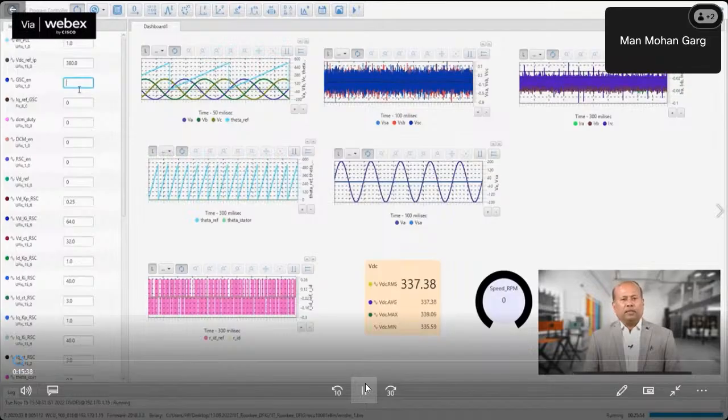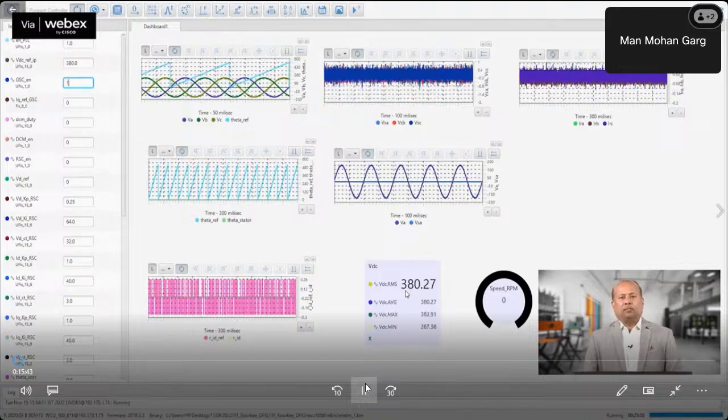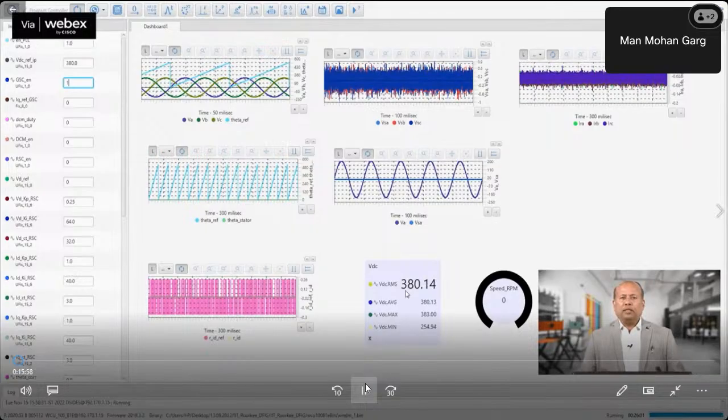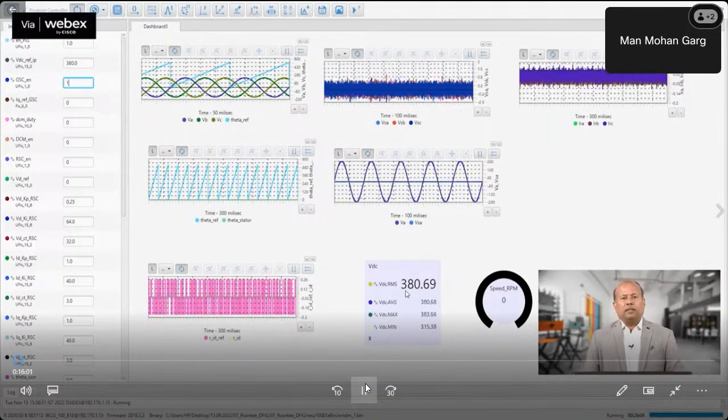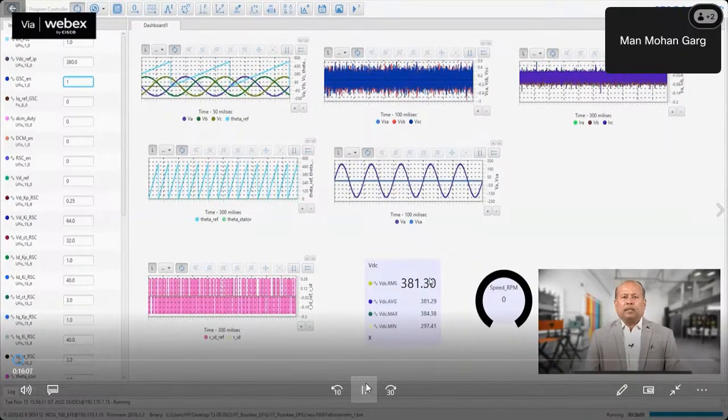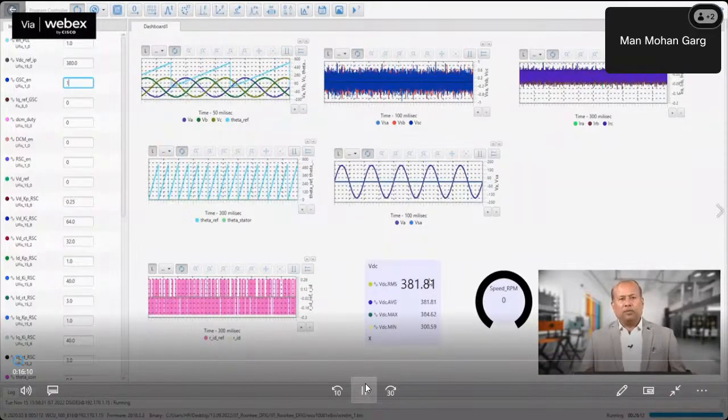Once the DC link is charged, we enable the GSC control to maintain the desired DC link voltage, which is set to say 30 volt greater than DC link voltage, that is close to 380 volts. We see that GSC tracked the DC reference voltage and measured DC link voltage is read as 385 volts.